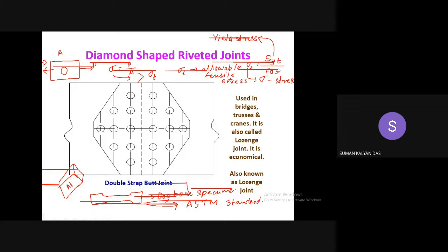Subsequently you have to decide upon a factor of safety. For ground applications, applications which normally are not flying, flying meaning rockets and aerospace systems, the FOS needs to be suitably selected. They need to be on the lower side so that the weight of the systems comes down. But for ground applications, normally the FOS is selected suitably high, so that we are always on the safer side.